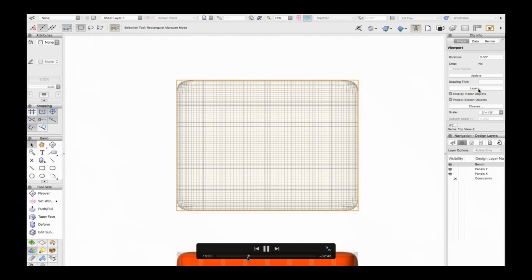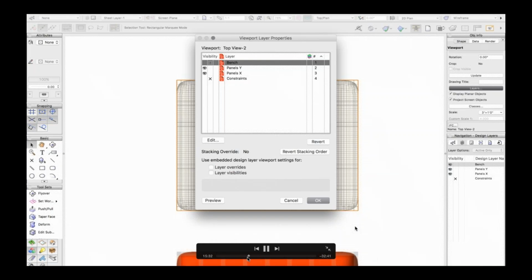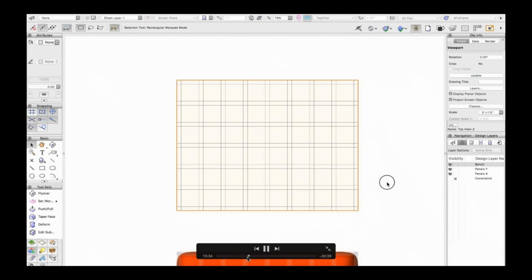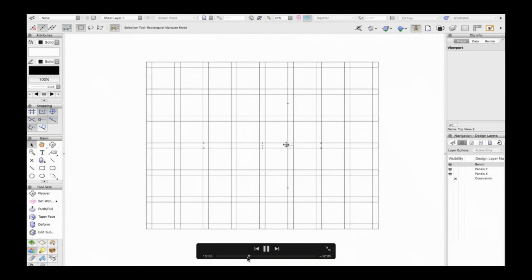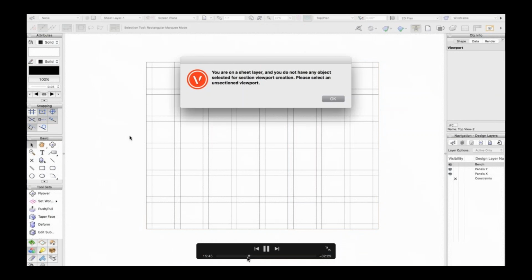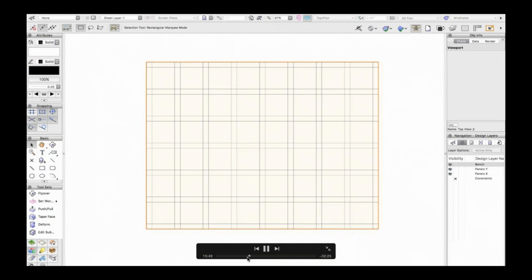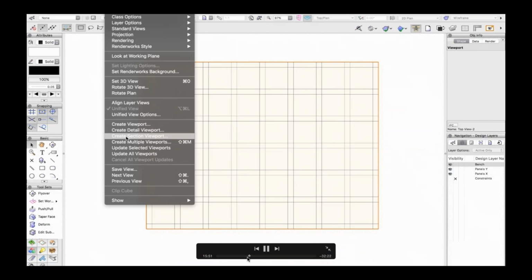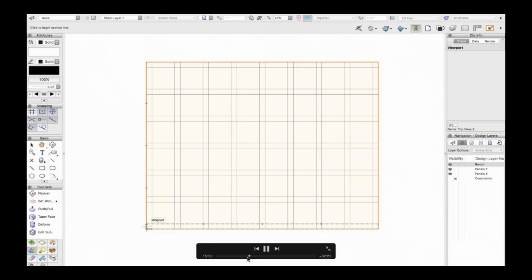Well, there's a little bit of a challenge here in trying to output information to, say, a template or a CNC router or something like that, where we're just creating these small panels. The solution that I came up with was to actually draw section lines through the object at every supposed panel, and that would give me a viewport for every panel in the X and Y axes.